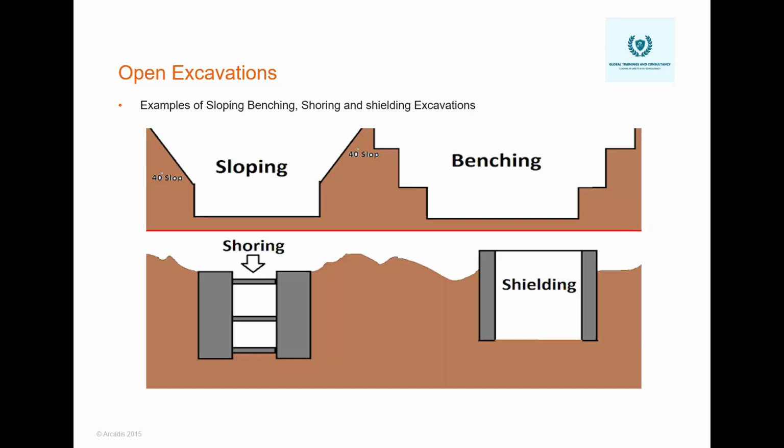When we have to develop or construct a pipeline, we put shoring. Shoring is steel or metal sheets which we put on the sides of the excavation, and these are supported with hydraulic jacks, so that any pressure from the outside, from the walls of the excavation, will not impact the protection, and people can work inside these two sides of shields.